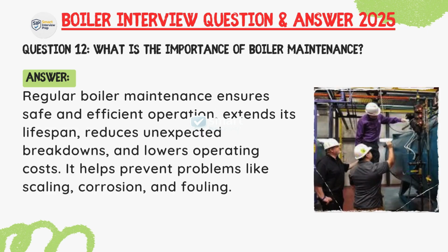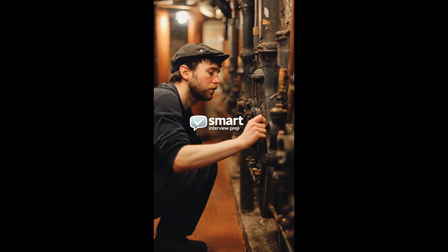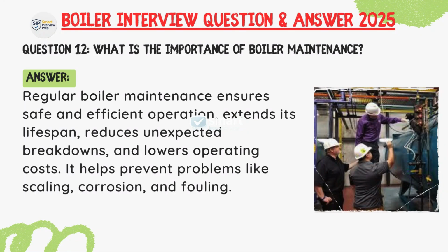Question: What is the importance of boiler maintenance? Answer: Regular boiler maintenance ensures safe and efficient operation, extends its lifespan, reduces unexpected breakdowns, and lowers operating cost. It helps prevent problems like scaling, corrosion, and fouling.